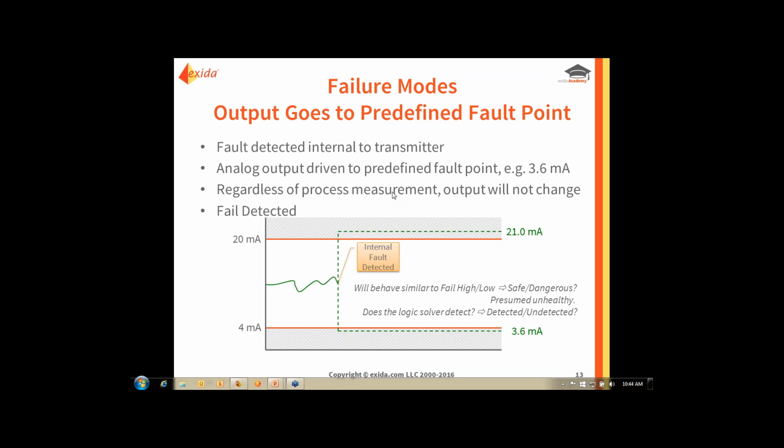So an example could be that you have a filter circuit as part of your output circuit, so you get a nice smooth signal. If that filter fails, one of the resistors could fail, the capacitor could fail in such a way that the functionality of the filter is lost, and your output signal becomes very noisy.